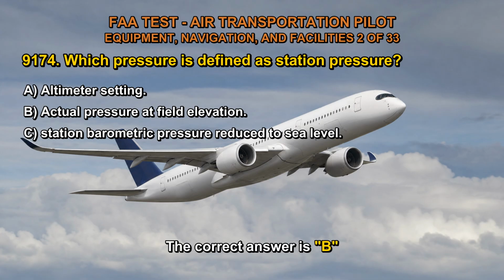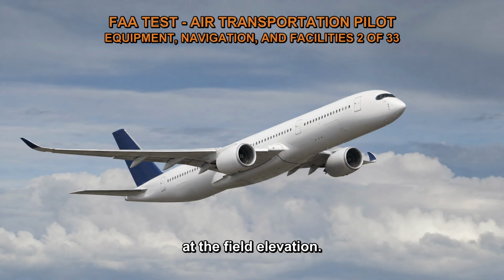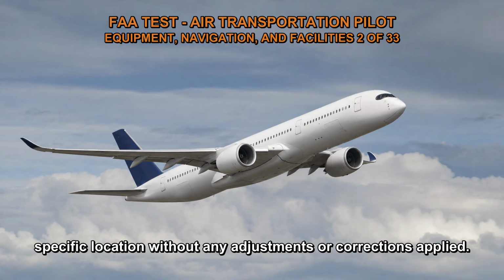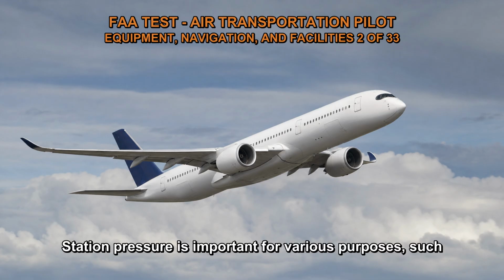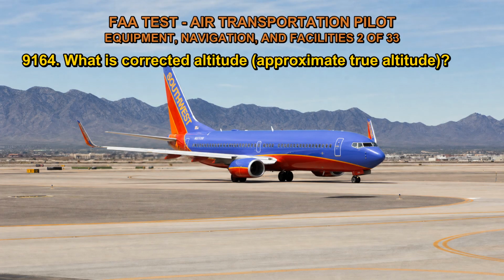The correct answer is B. Station pressure is defined as the actual pressure at the field elevation. It is the atmospheric pressure measured at a specific location without any adjustments or corrections applied. Station pressure is important for various purposes, such as calculating density altitude or determining the local weather conditions.